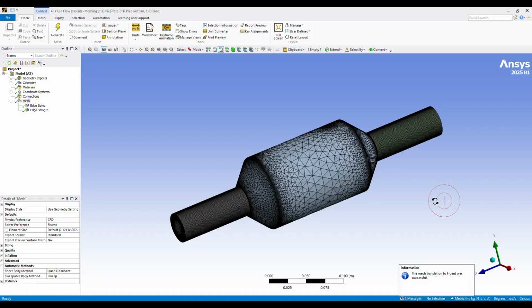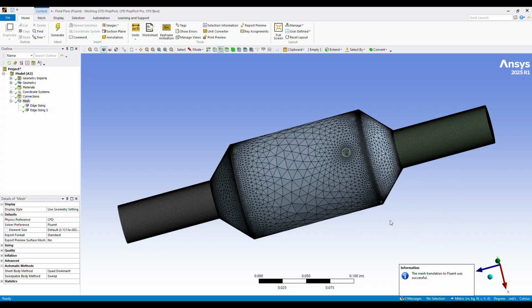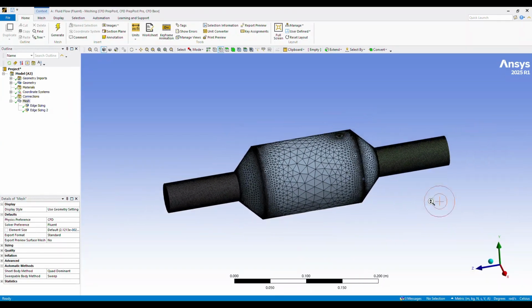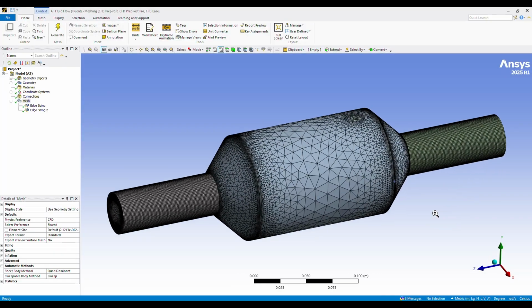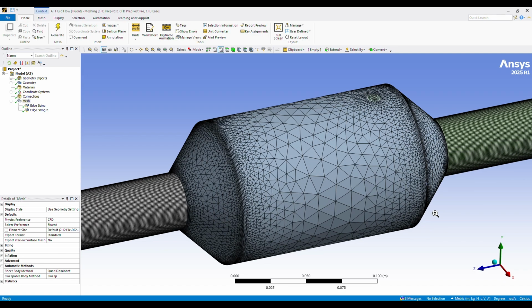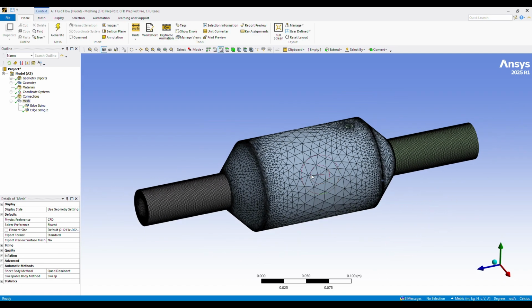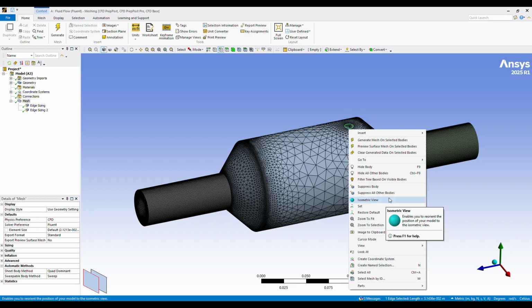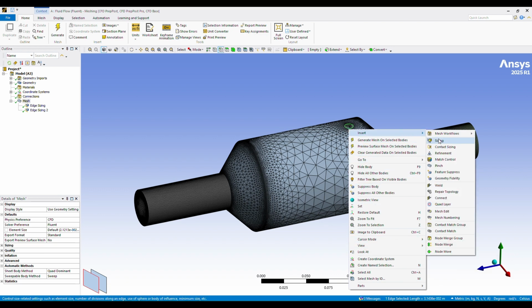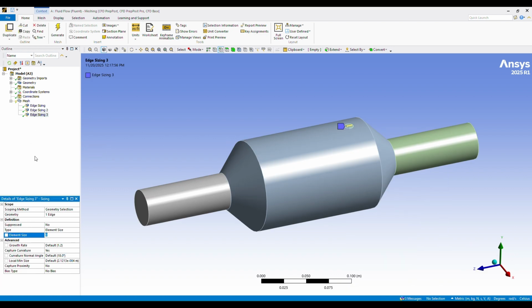So I'm changing the mesh. Now I need to put the inflation layer at the leakage point, that is at the extrude cut sliced material. So I'm sizing the leakage corners.